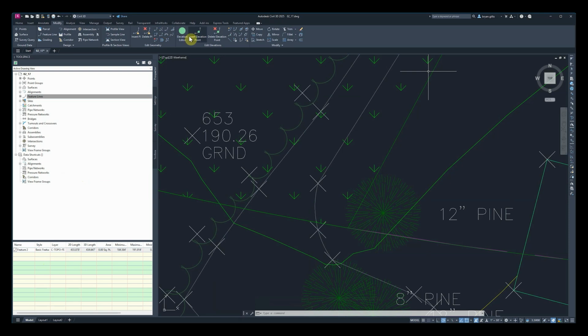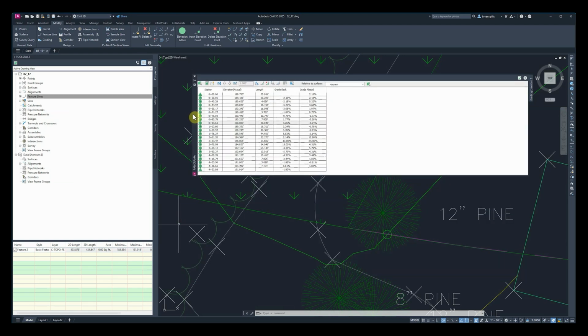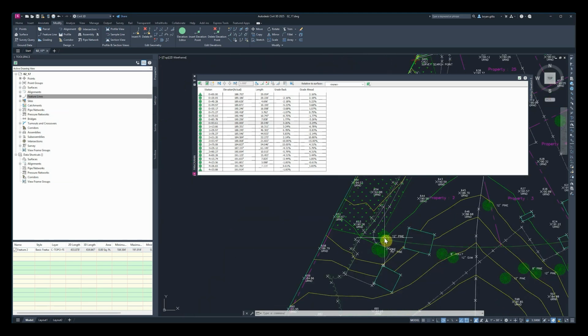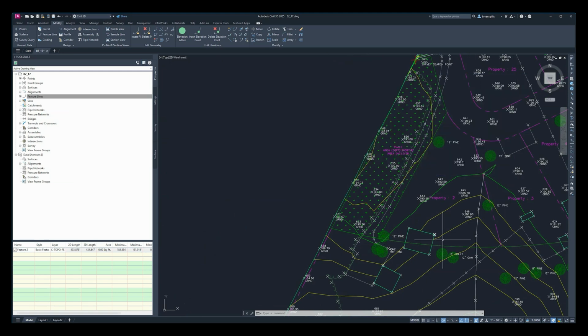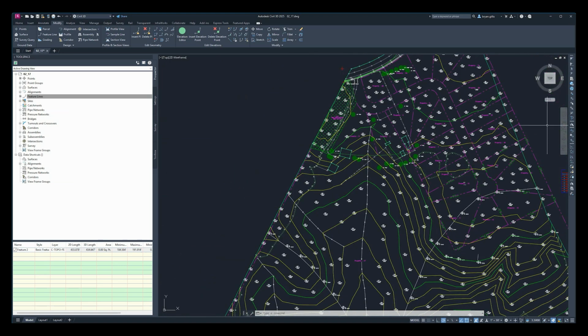And we'll hit our elevation editor, and we'll go back and check out that feature line, and we can see where it was created right here. 190 feet exactly. It's highlighting our point for us. So again, quick, easy ways to check. Go ahead and hit that green arrow to close that view. We don't need to make any additional changes. And with that, we have completed part 17, editing elevations for feature lines. Go ahead and close your drawing.